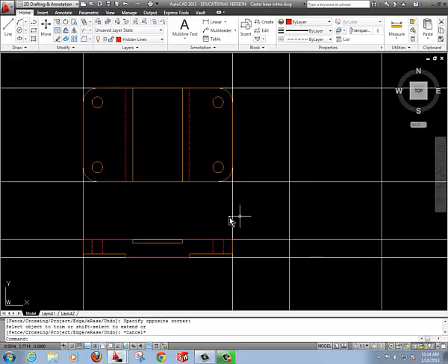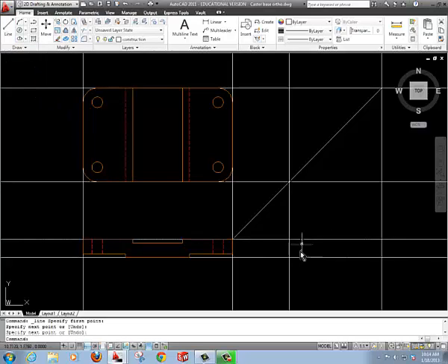And for this one, we're going to use a miter line. So we're going to go to our construction line. Use the miter line that goes from this point to this point. And this line will give us the information that's going to go on this surface right here. So now we can go over and start drawing our side view. We're going to object line, and we know that our object line is going to be something similar to that. So the shape of our right hand side view is like that.